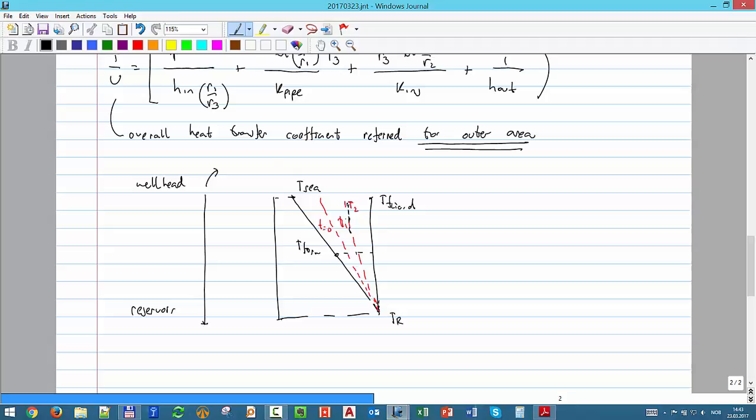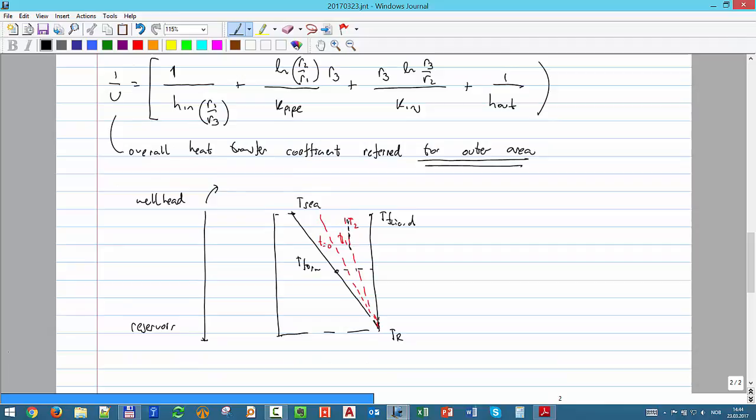So for some well models you see that they have an option to choose how many days into production you want to calculate. They apply a very similar equation, but then they ask for which day you want to calculate: 1 day, 20 days of production, 100 days of production. For some wells it might take a long time, maybe 3 months, to warm up all the area around the wellbore.